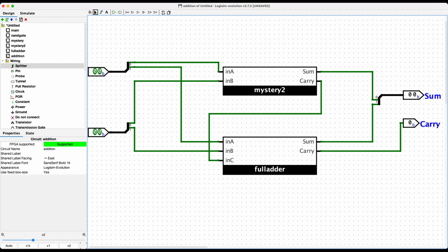So this is sort of the most naive way to build an addition circuit. There are more exotic ways that try to speed things up. But in terms of the structure here, does it make sense how this is supposed to work? Anything else we do is just trying to speed it up by doing parts of the computations in parallel, if we could. In reality, that's of course how a modern addition circuit is going to work. If I wanted to build a little 8-bit computer, this would probably be fine. Just 8 of these things, 8 full adders.